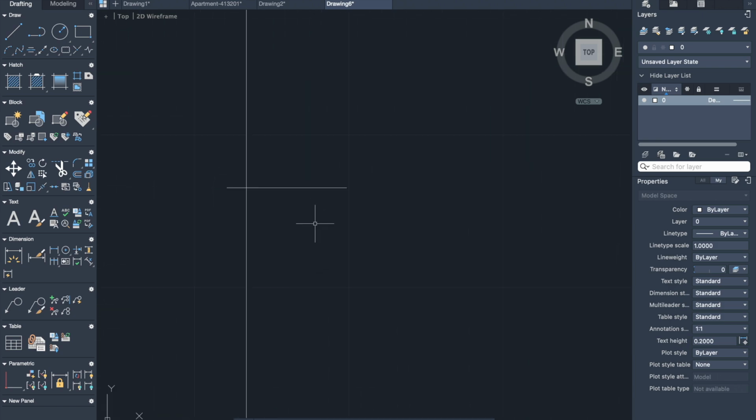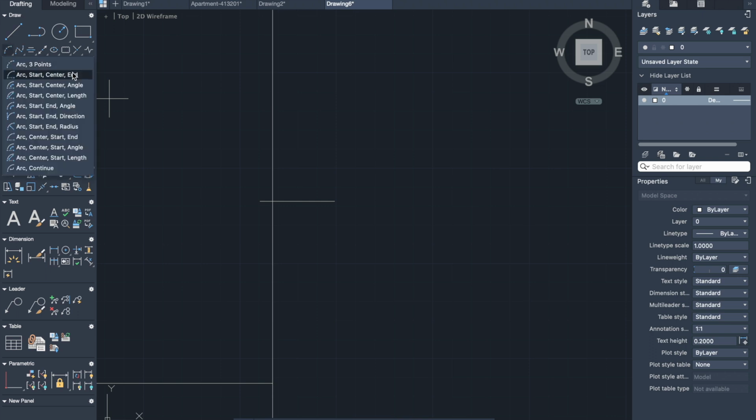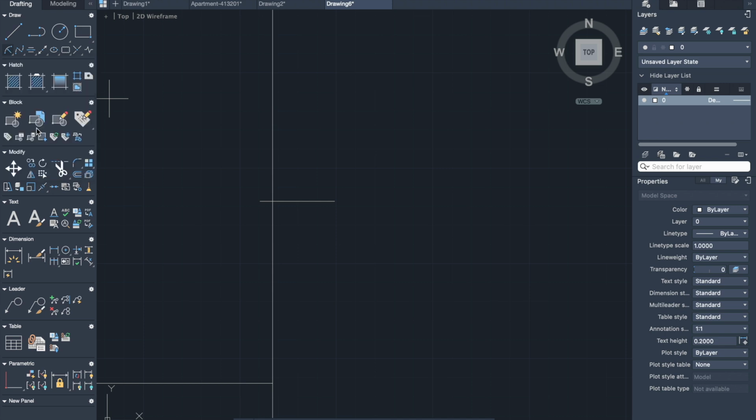And then if I want to create a doorway, I can go to the top left as well, and there's a function here in the top or bottom left of that drafting toolbar called arc. Now if you hold the bottom right hand arrow, it will bring up a few options: arc 3-way, arc start and center. Today I want to use the arc start and radius function. So for this, it's going to allow us to specify a start point, an end point, and then the radius.